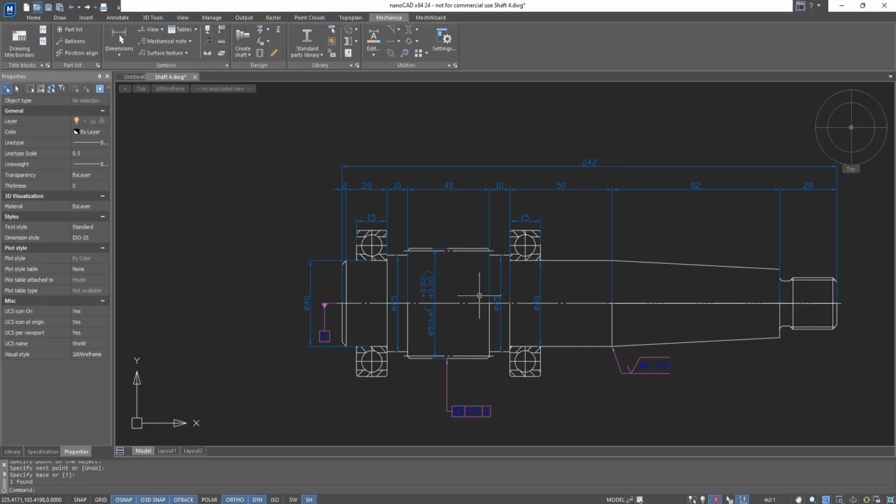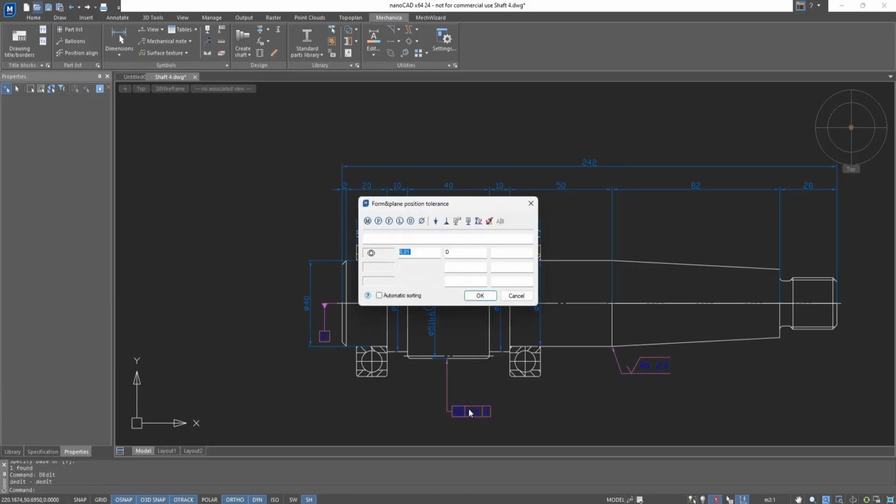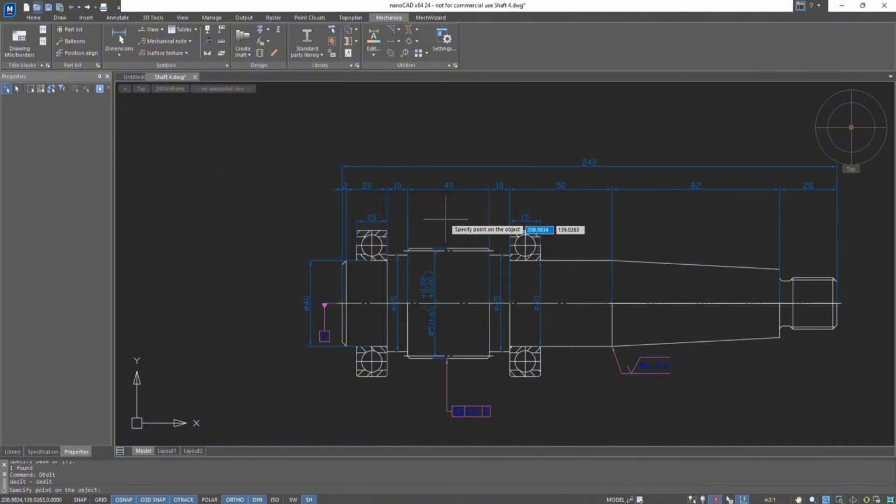We will set additional callouts for the first, fourth, and fifth sections of the shaft. For this, we edit the tolerance designation. Double-click to open the editing window and select the Set Additional Base icon. Place and connect 3 additional callouts to the tolerance sign.